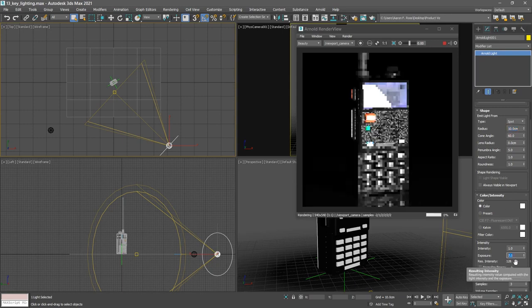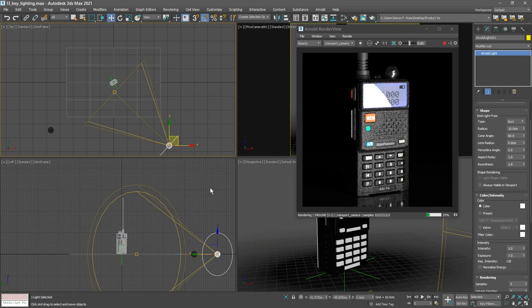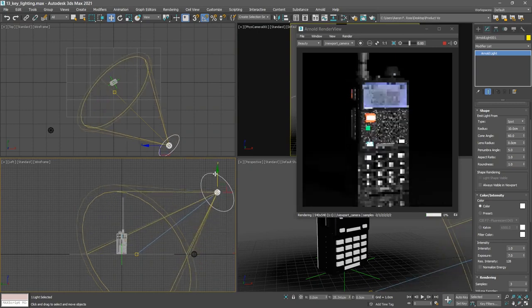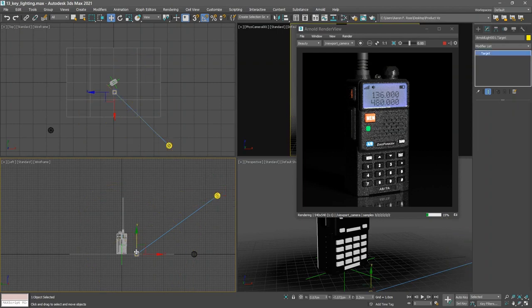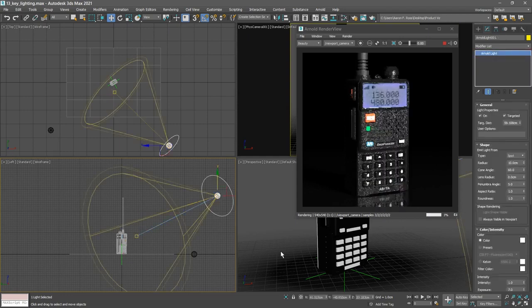And we can position that light. We'll grab the Move tool. It'll need to be moved up off the ground plane. So select that light and move it up in the left view. And we can also move the target up a little bit. I've got some values that I know are going to work, so we can plug those in. I'll select the light, and we'll give it an X position value of 27.